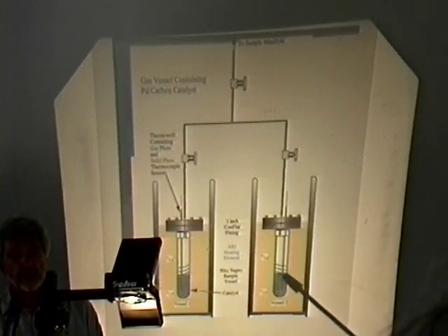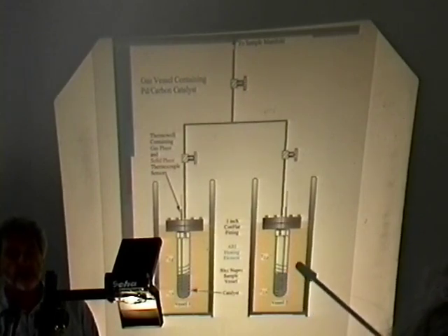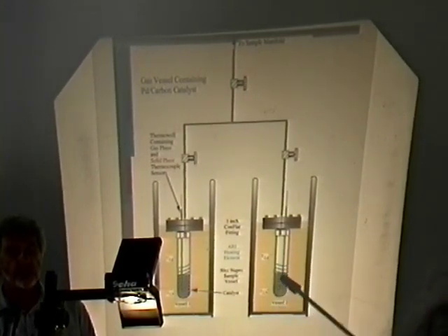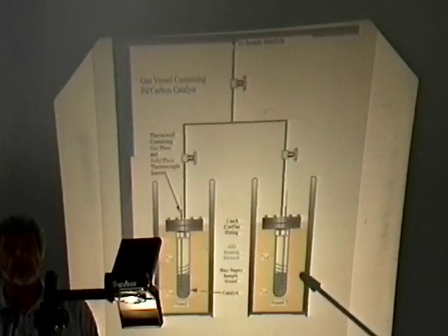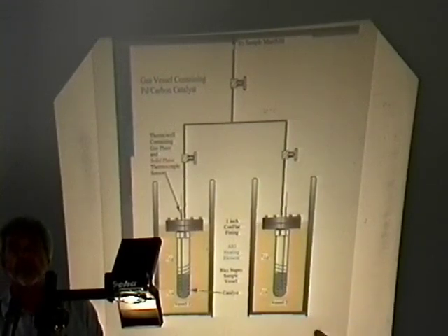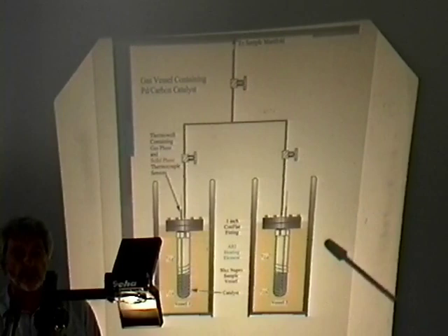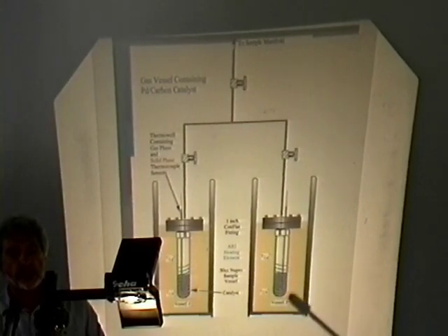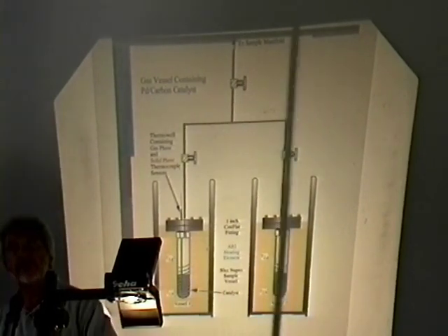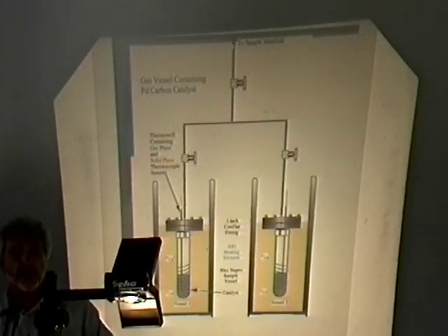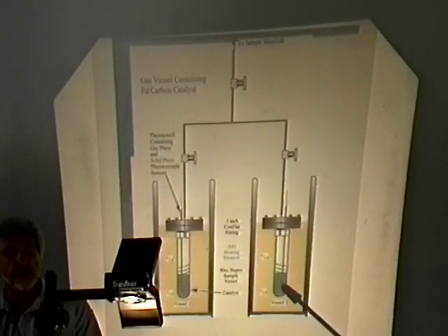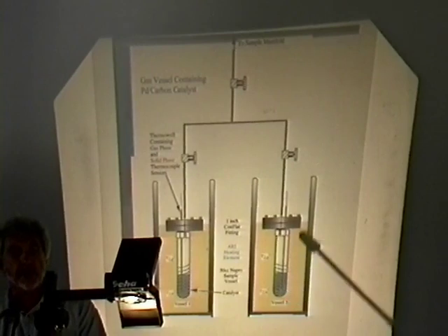I should describe the heating arrangement. There's an electrically powered heater helically wound around the bottom of this surface. This yellow material here is a solid insulation. The whole is packed inside a stainless steel dewar. So the object is to heat the catalyst and allow heat to leave this system in the axial direction. So there's a gradient of temperature from the bottom of the cell in the catalyst bed to the top.